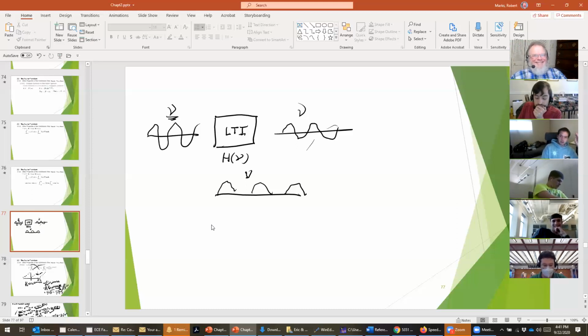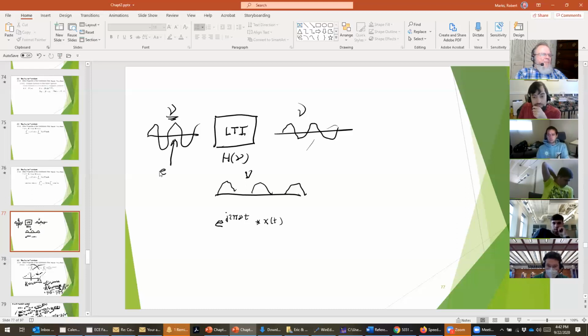No, my question was more about the theorem, the actual equation. Like, we had x of t convolved with e to the j 2 pi nu t equals. Yes, I was talking about that equation. So if I had an actual value for nu, it would be one specific frequency that I'm testing with my system, basically. Exactly. In fact, this sinusoid which we're putting in here is e to the j 2 pi nu t. When I came back and looked at it, I was wondering why we didn't use u, and I rewatched the lecture, and I got the impression that it's because it's a single frequency. It's a single frequency, yes.